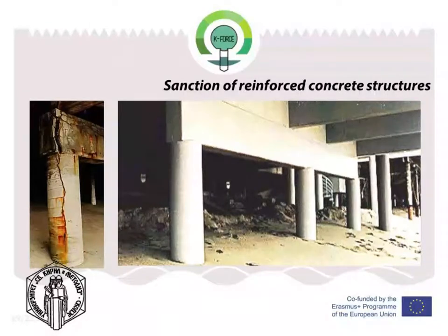Some form of finishing may be required for aesthetic purposes. In terms of fire protection, possible occurrence of damage, and protection against UV radiation, a finishing layer can be crucial to the long-term integrity of the strengthened structure. Different types of finishing layers can be provided, such as painting, shotcrete, or fire protection panels. The compatibility between externally bonded reinforcement and the finishing layer should be ensured.